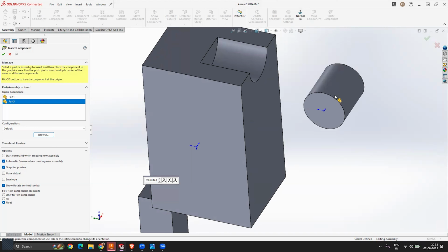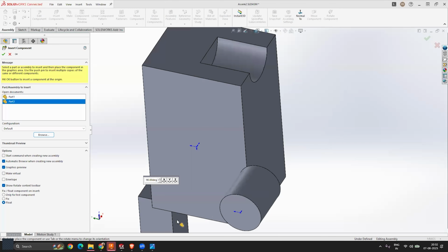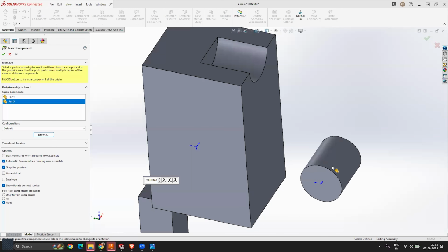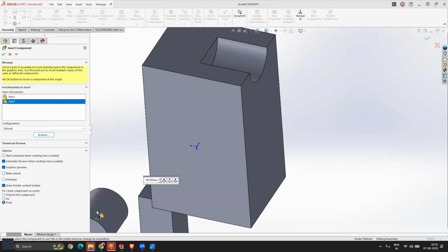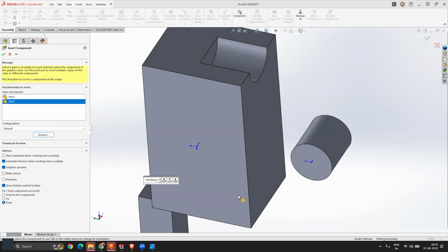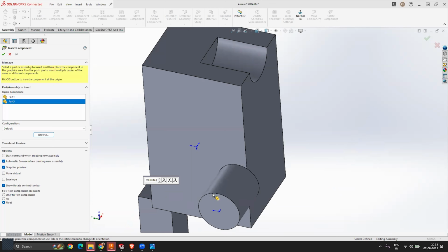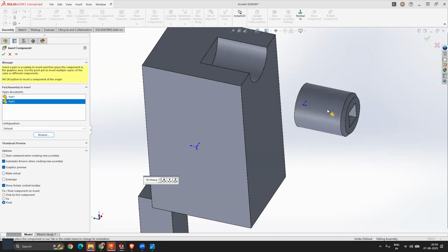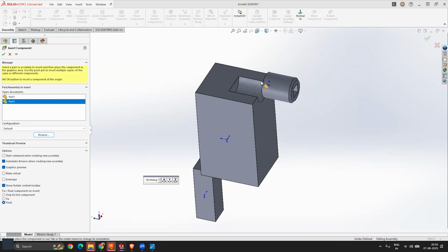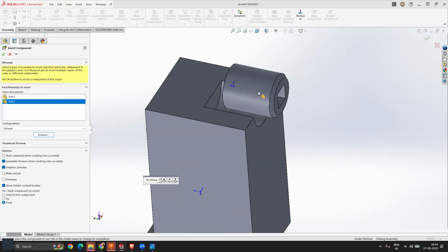And how can you find in which direction you have to rotate? If you try these things randomly, that is going to waste time, right? So you can estimate. You'll see at the bottom corner, all the axes are defined. The Z is pointing upward, X is towards forward, and Y is towards the left side. So if I want to rotate this part to the correct orientation, we first rotate it using this Z gizmo. Here you can see, maybe if I rotate 2 times, this is the orientation in which we want to place it. Since the orientation is correct now, I will simply go near that area and click. So it will get placed somewhere near that area, right?